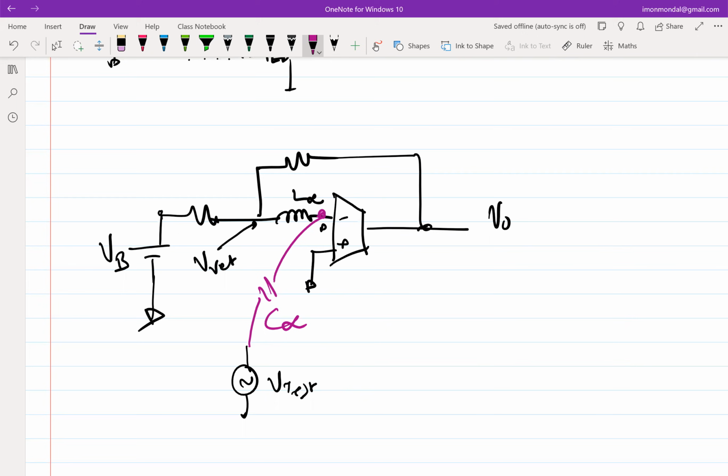If you remove the feedback and debug, you are essentially doubling your effort, because you are first optimizing it for open loop, then you are optimizing it for closed loop. There's no point. You can basically put everything in negative feedback and start optimizing them. And the breaking of the loop can be done by these L infinity, C infinity things.